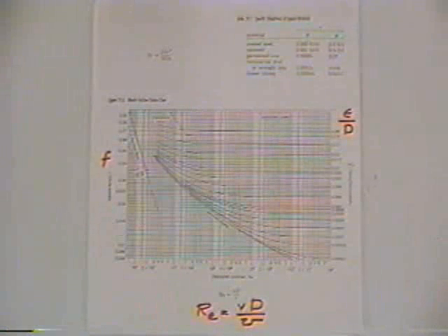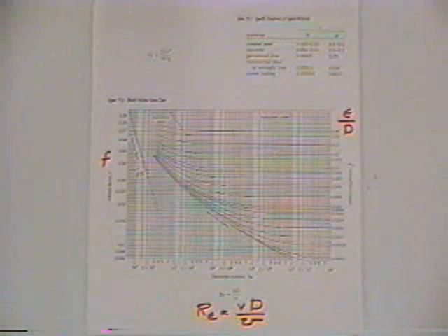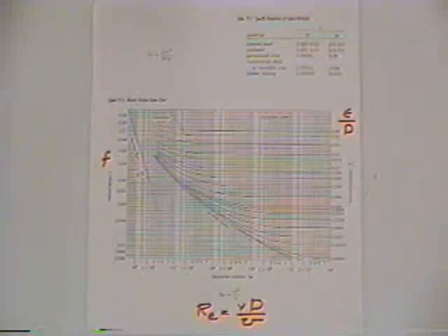And there are different areas of the Moody diagram. And so another concept in fluid mechanics, which comes into play here, which we mentioned very briefly in another application, is the concept of laminar versus turbulent flow. And again, laminar flow is where you've got smooth layers of flow, just smoothly flowing one layer over the other. Turbulent flow is random motions, as the fluid particles are going this way and that way in a random fluid flow field.